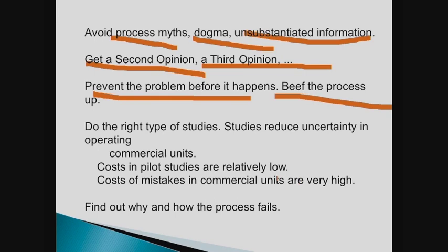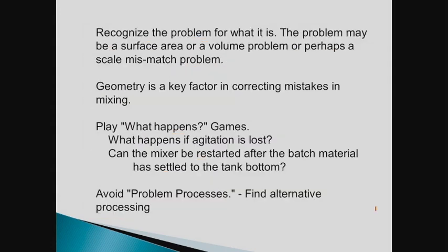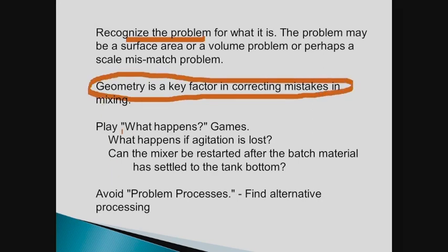You want to beef up the process. You want to do the right type of studies. Cost of pilot plants is relatively low. Cost of mistakes in a commercial plant can be very high. Find out why processes fail. Recognize what the problem is. Geometry is a key factor in correcting mistakes. Play what-happens games. What happens if I lost agitation? Are the solids all going to settle to the tank bottom? You should avoid problem processes.